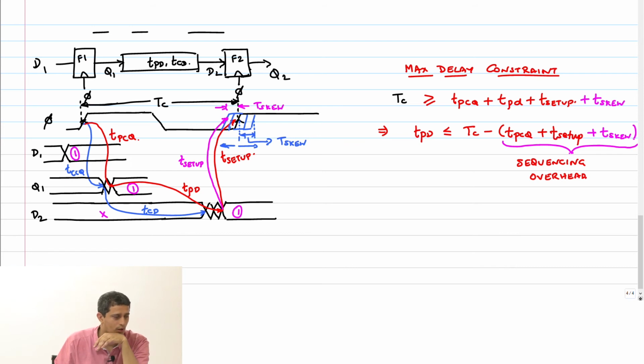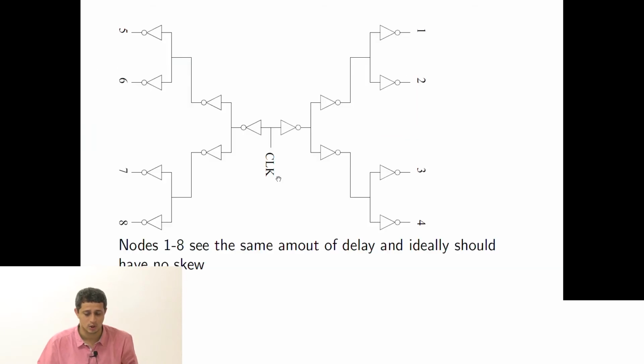D1 it arrives. So like I told you, the reference you have to make with respect to one clock. My reference clock is not this clock. It's not with respect to this clock that the leaf nodes start deviating. This guy, clock 1, the flop connected to node 1 will become my reference clock. With respect to that, what happens to the next node is what we are saying.